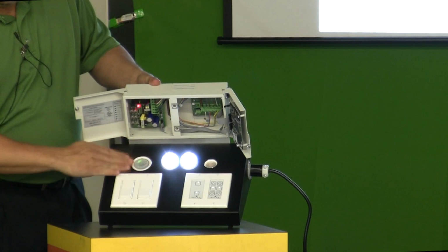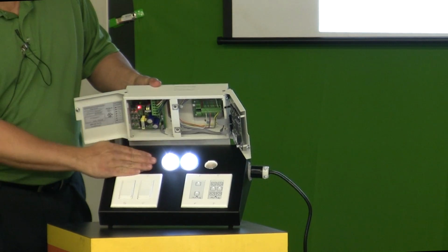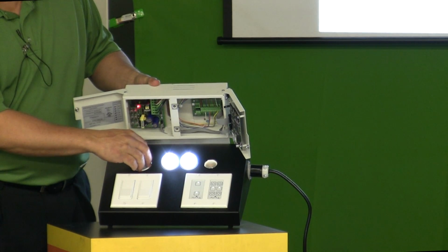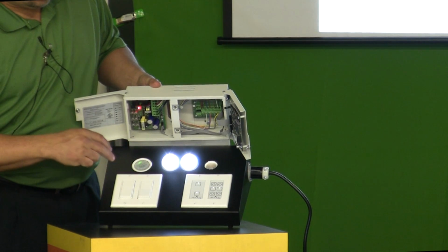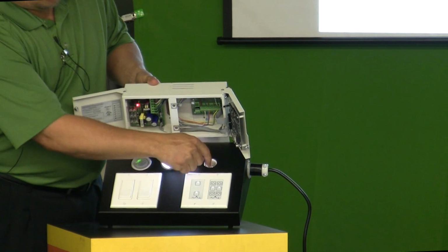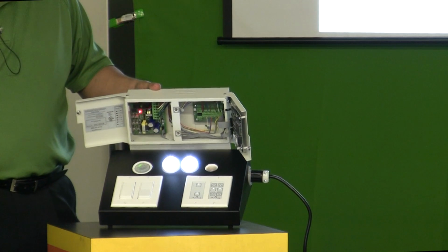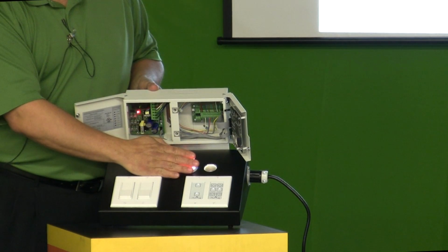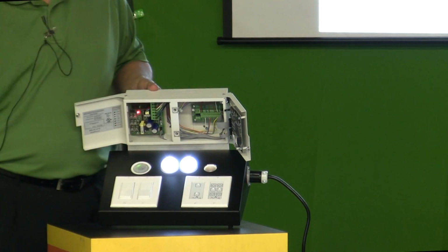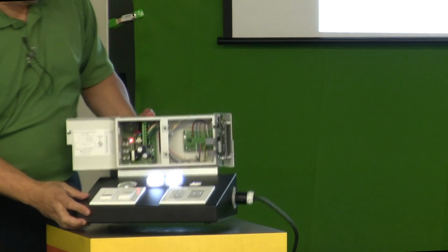This happens to be an occupancy sensor. I'm not going to wait around for it to time out, but that's basically what we have in this module. If you want to come out, I'll show you how it actually operates in a little more detail. This is a dimming photocell so that you can actually see what the light level is in the space, and we can implement a dimming control strategy, and I've got software in that over there if you want to come over and take a look at it.